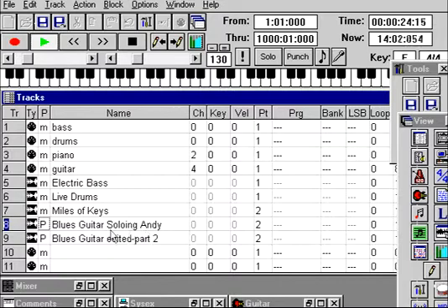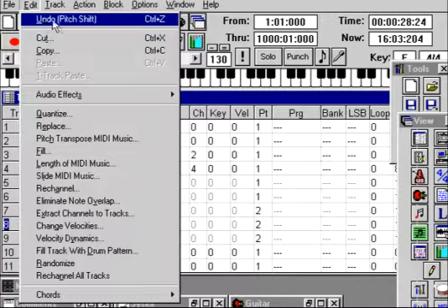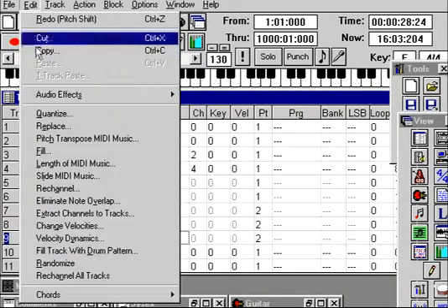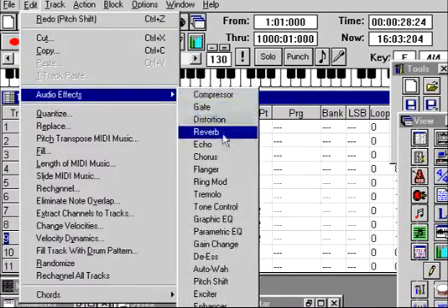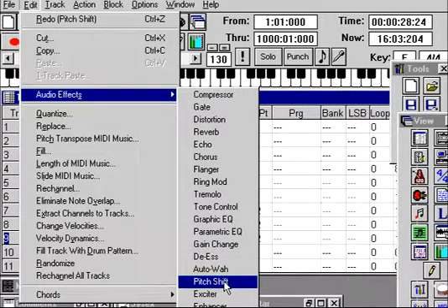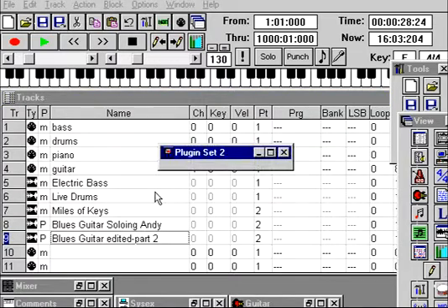So I'd say that's not enough, so that's okay. What we can do is go into the Edit, Undo Pitch Shift, and press that. We'll get the original 2 channels back, and we can go back and revisit our audio effects, and we're going to say back down to Pitch Shift, and this time we're going to set this maybe a little higher. I guess maybe we were right the first time. Let's set it back to 50.